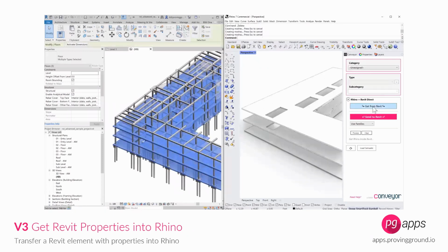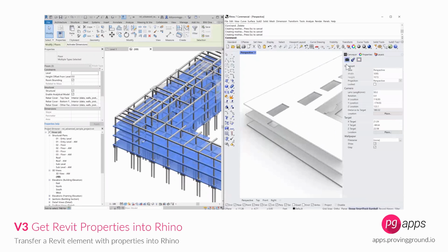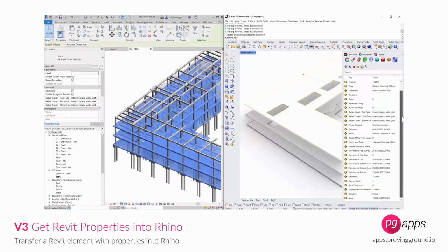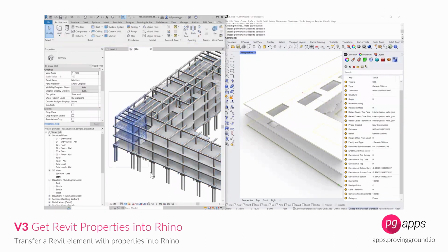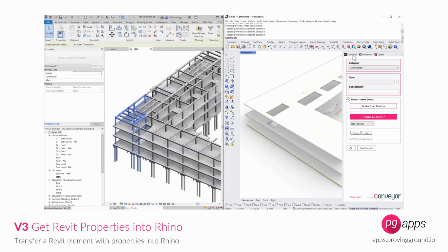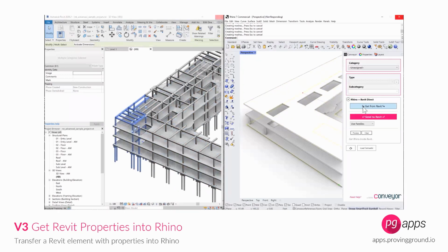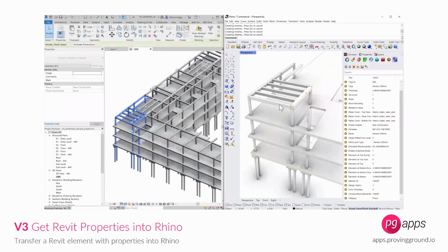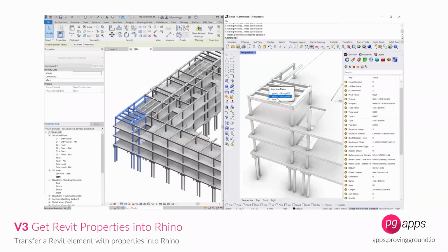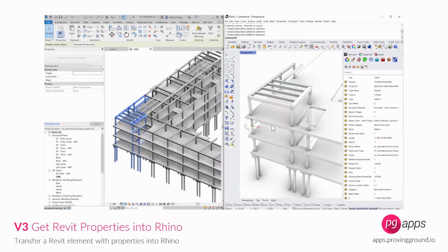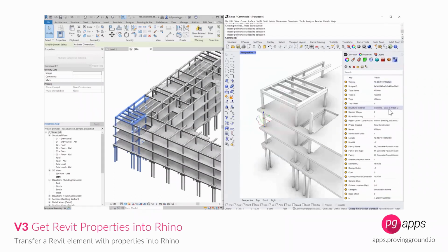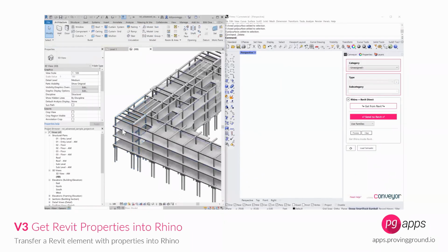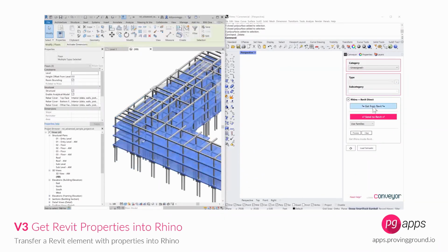So not only are you able to grab geometry out of the Revit environment and put it into Rhino, but those properties that are assigned on top of the Revit objects are exposed in Rhino after the transfer as user text and data that can be accessed and reviewed, or even tied downstream into other use cases, like creating an analysis tool in Grasshopper, for example. We think that the availability of properties and the transfer of data between applications is almost just as important as the geometry itself.